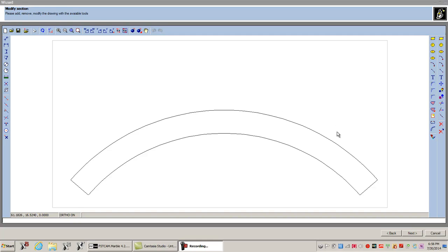On the piece that's the scrap, you will see a bevel. As you're cutting with the blade and the C-axis is rotating and the Z-axis will be going down, it'll be forming a bevel on the scrap. But now when I want to cut the inside, I don't want a bevel on my finished product. I want my finished product to be square, 90 degrees from the profile view. So I want the bevel on the scrap.